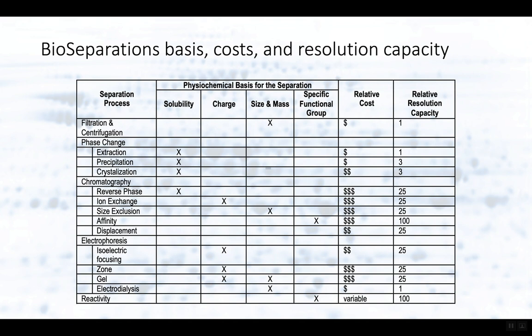Okay, zone electrophoresis and gel electrophoresis are kind of the most expensive. It's very much like chromatography. You have a small amount of material you load at the beginning of a column. At the end of a column, you isolate the product you want from other peaks that are coming through. You have to wait until all that's out before you can load the next batch on. It's inherently a batch process. It's also dilutive. What comes off the column is typically less concentrated than what you put on. It's not quite as bad as chromatography, but it's still dilutive.